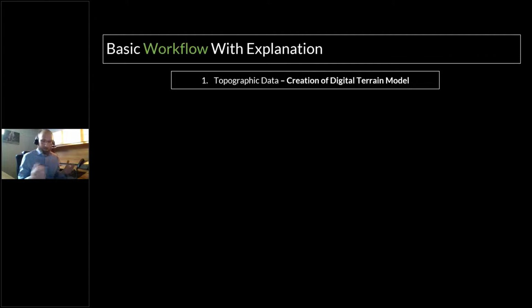So you have to go do a bunch of field work, a lot of walking around, and select a route to pursue. So you're figuring out your preliminary alignment, your P line, then you survey it, and you're usually only getting a set width for survey data. And then when you come back into the software to really refine the plan,